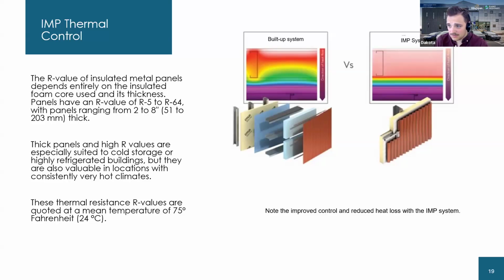That's primarily because of the fasteners that need to pass through the insulation on that multi-component system. With the insulation sandwiched between two steel sheets in the IMP solution, we can see much more consistent thermal performance, meaning that the backup wall, again, doesn't have as much opportunity to get cold enough for condensation to occur. This eliminates the risk of mold, mildew, grandma's basement smell, structural damage, that kind of stuff. Whereas here, we have those Z-girts, again, often conductive materials, and that allows a much deeper temperature discrepancy between those two systems, meaning that this backup wall could potentially get cold enough to allow condensation to occur. We super don't want that.